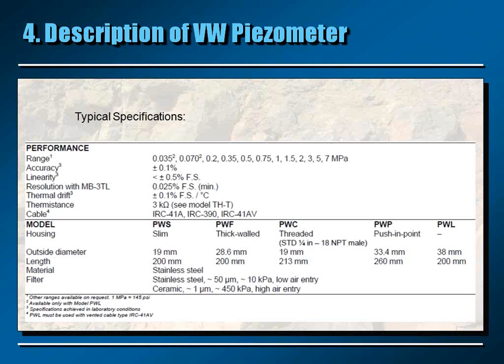And this vent tube is a small plastic tube that is located in the electrical cable. At the end of the vent tube, you will have desiccant included in a cartridge, and this desiccant must be changed periodically. Its role is to prevent any humidity ingress or infiltration through the tube, which would damage the sensor.